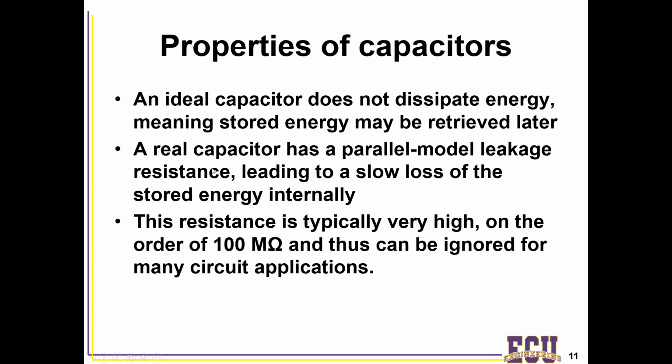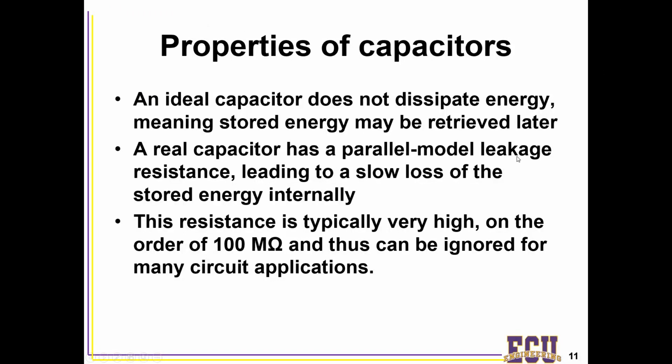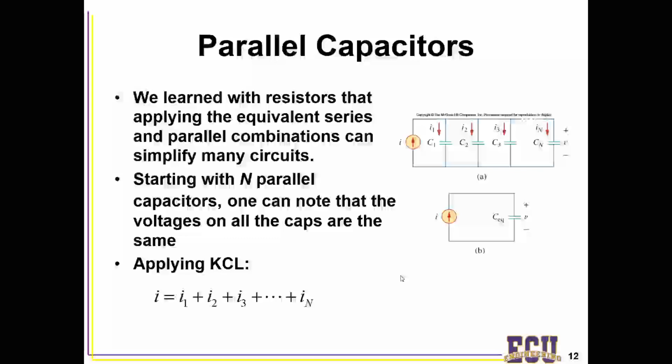And a real capacitor actually does have a resistance in parallel with the capacitor, so that will actually discharge the stored charge over time. The resistance is typically pretty high, so it's 100 mega ohms there. Sorry, I misspoke. I said it was small. It's actually quite large. It's nearly like an open circuit, but it is a real and finite resistance, so there will be some discharging.